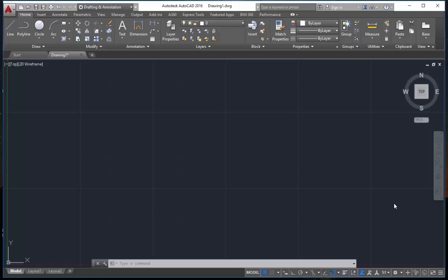And today I am going to explain to you about 3D and 3D basic objects. Okay, so till many days we were working in just 2D. Okay, it means that the workspace I had kept it as drafting and annotation. So now if I am going to work with 3D, I am going to change my workspace over here. Okay, so first here I'll tell you how to set the workspace.